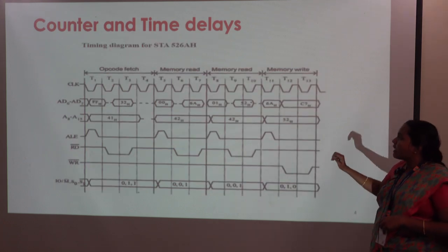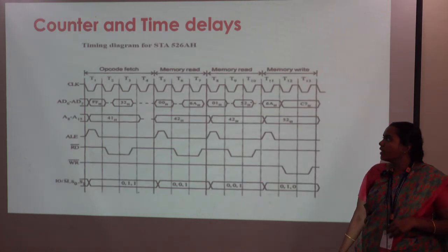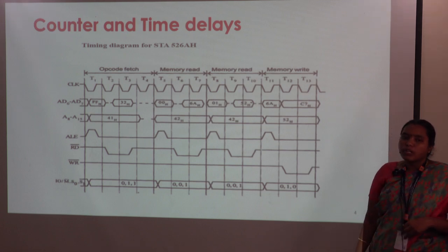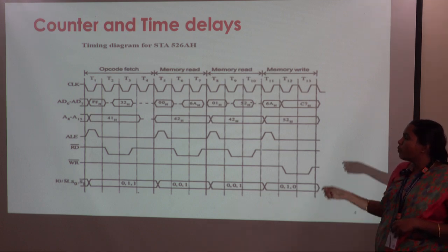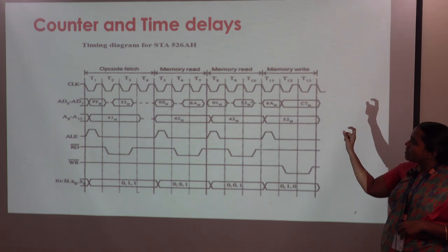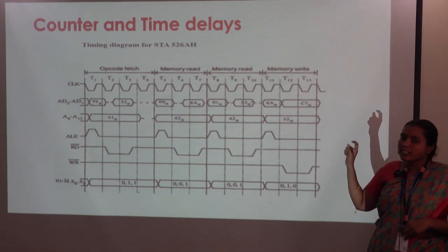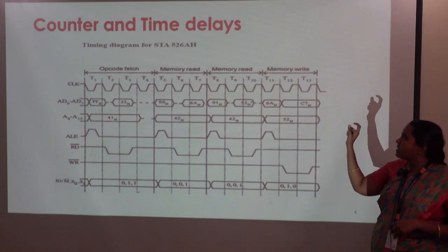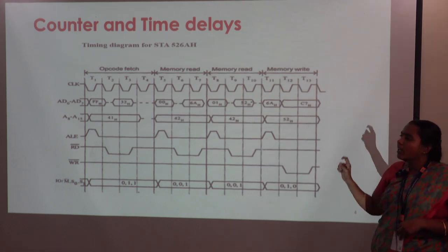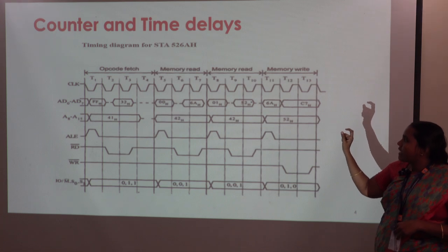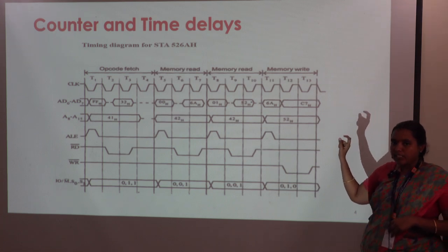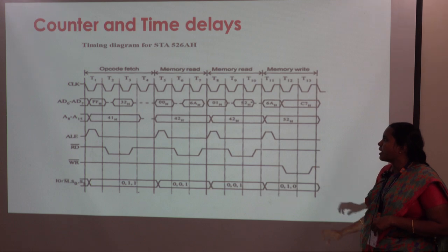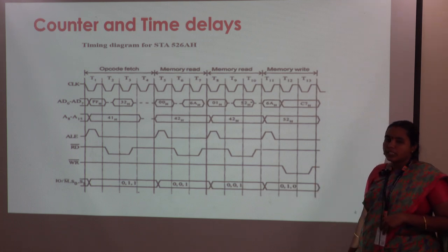This is the timing diagram for STA 526AH, where H is hexadecimal. STA 526A means the accumulator content is stored to the memory location 526A. This is the timing diagram for STA 526A.